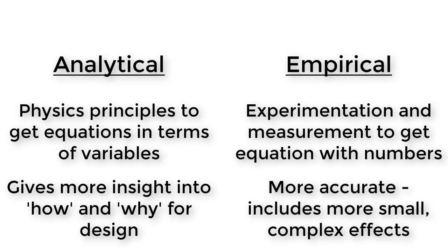We could do that by analytically modeling the fluid responsible for the damping, but that's starting to get really complicated. We would probably estimate B by testing the fluid to see how much force it produced for certain values of velocity. So we would have used part analytical and part empirical methods to create our model.